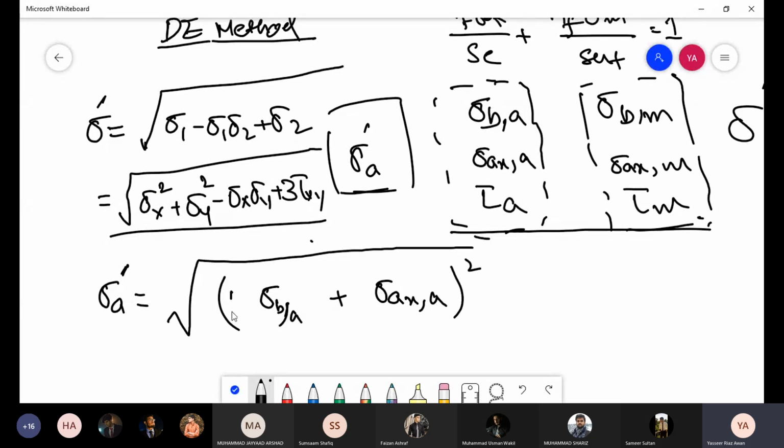And also remember to use fatigue stress concentration factors, and remember that these factors would be different for the same loading and same geometry. This factor would be different for bending and for axial, okay.